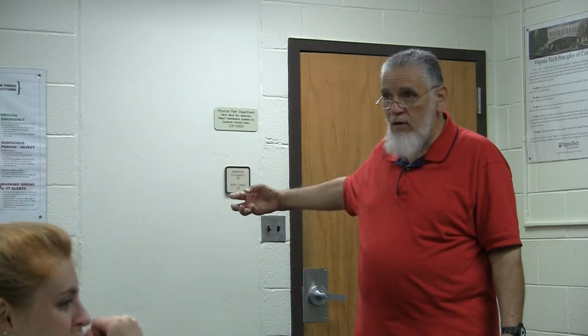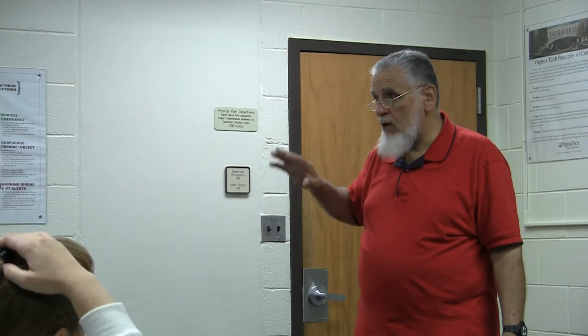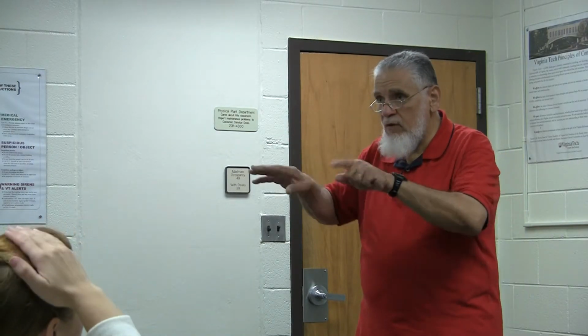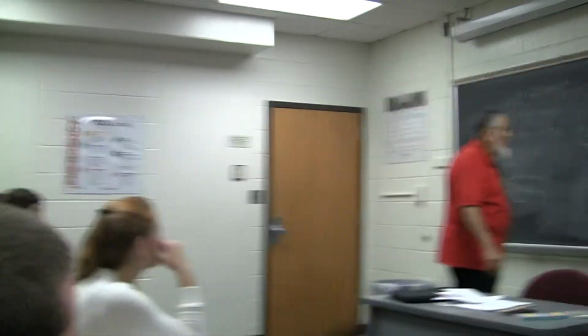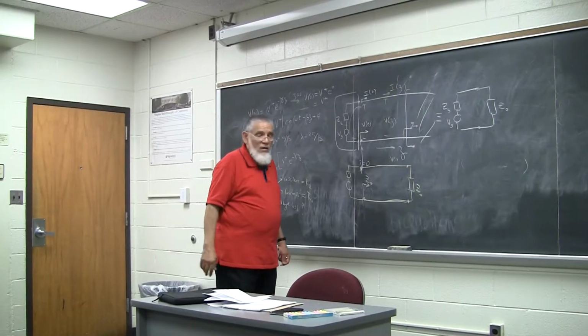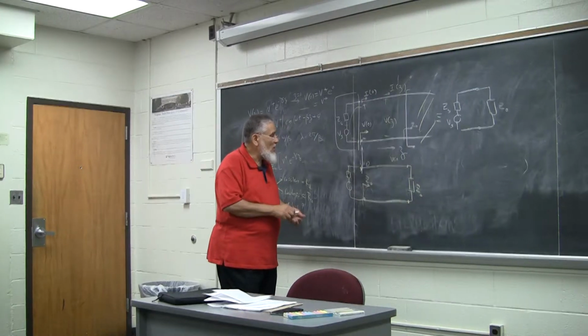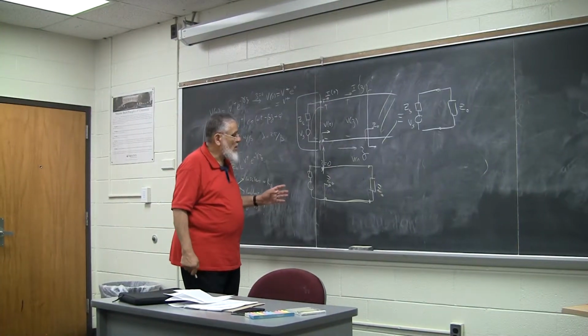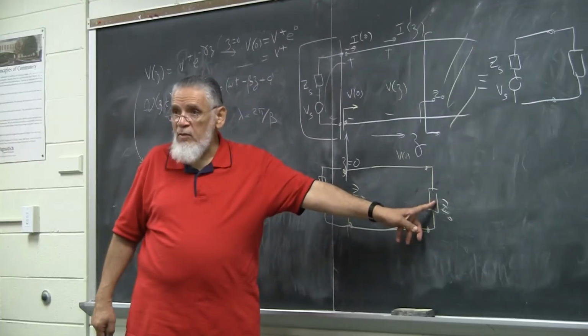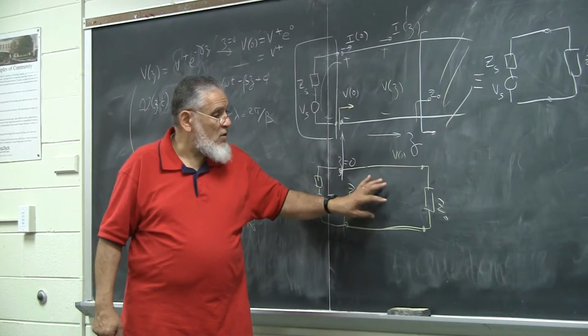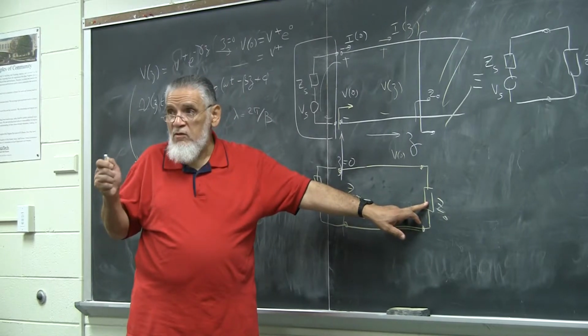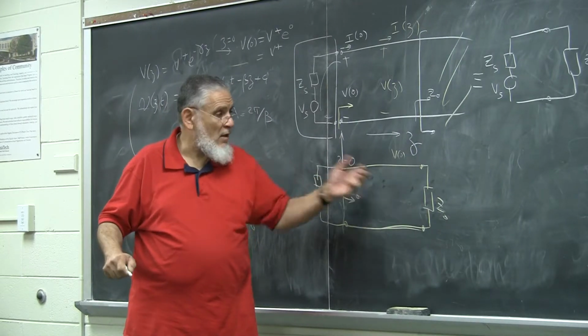So they come up with special material that basically absorbs the sound waves so they never come back. Mostly it's made out of loose fibers, fiberglass and many other things like that, so the sound waves scatter around and never find their way back. Mostly fluff material that's close enough to air that the signal goes in and doesn't come back. So here it's going to be the same: this is 50 ohms, all you need is just a pure resistance of 50 ohms that will absorb your signal, and nothing will come back.